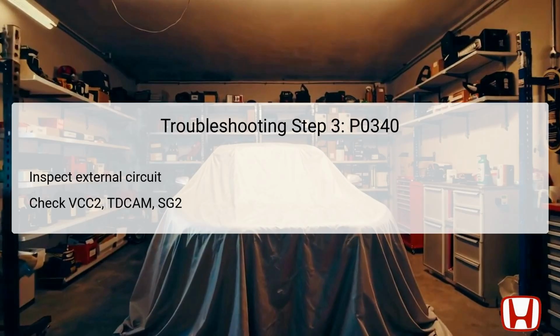Begin by ensuring that the CMP sensor A 3P connector and the PCM connector E 80P are both disconnected to facilitate a safe inspection. Check for open or shorted circuits by measuring resistance levels between the terminals. A normal circuit should show less than 1 ohm in resistance for VCC2, TDCAM, and SG2. If any abnormalities exist in these measurements, it indicates issues within the wiring or connectors, necessitating further probing.